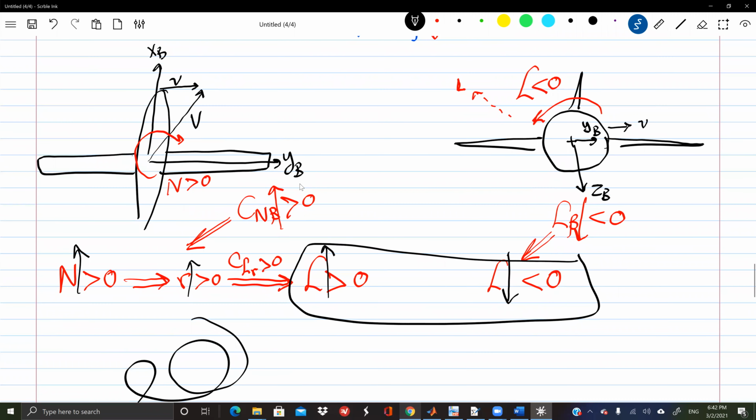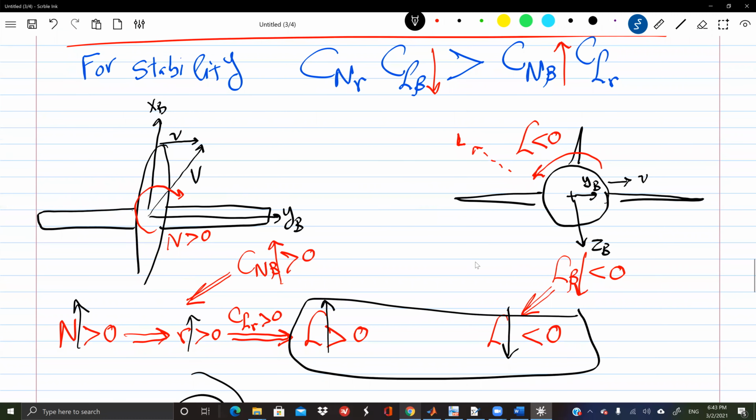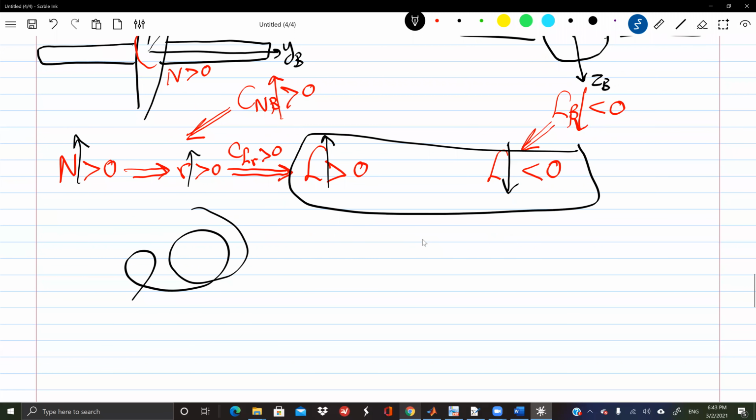So this gives you an idea about how things are really coupled together, and how even though you have stiffness, you have spring in each direction individually, it's not sufficient for a multi-degree freedom system, because things may interact with each other, causing instability for the overall system, even though each axis on its own is stable.